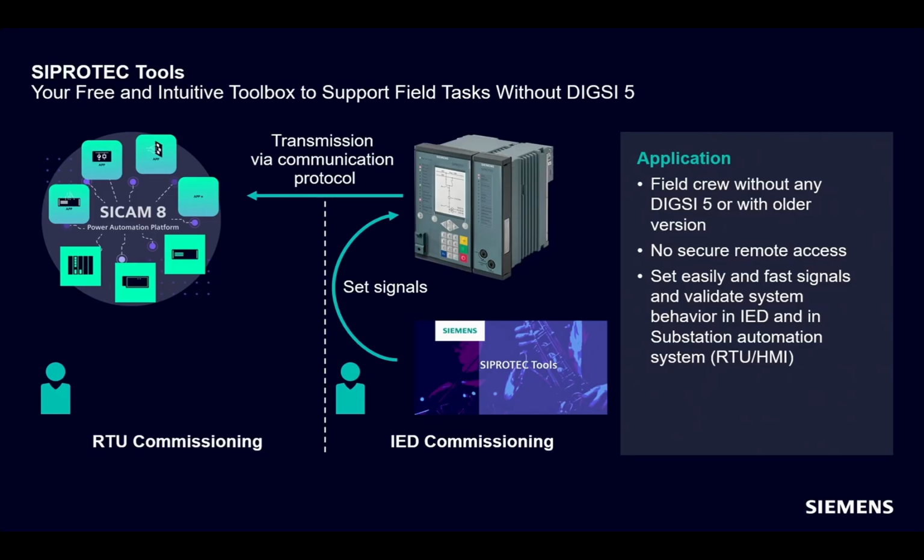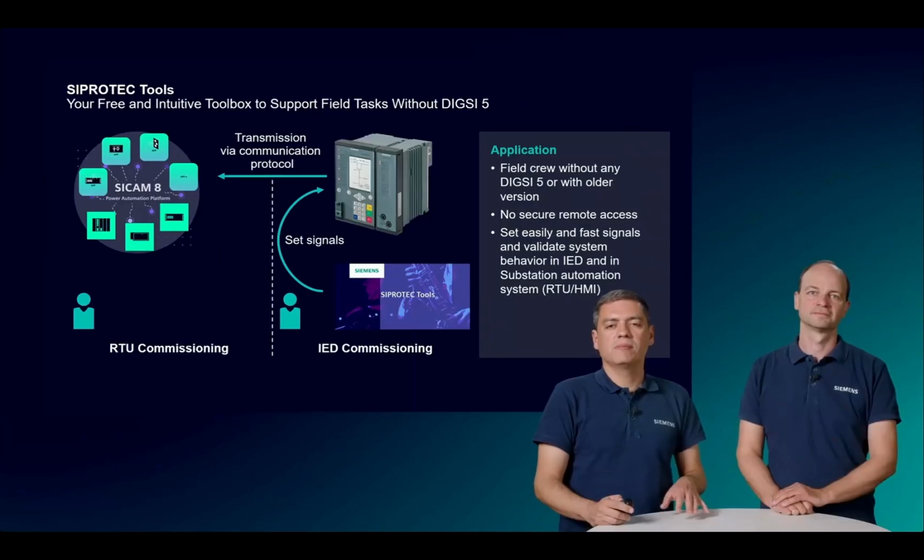You just need to connect your computer to the SIPROTEC 7SX800 device, run SIPROTEC tools, and use the signal test option to simulate everything you need, whether binary signals or analog signals. In this example, we initially show the simplest test in which the signals are tested only internally in the SIPROTEC 5 device to validate the configuration that was done.